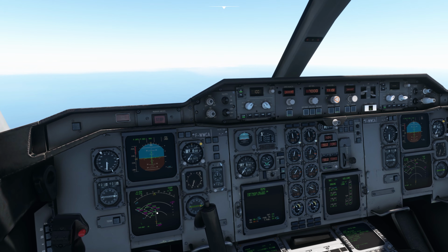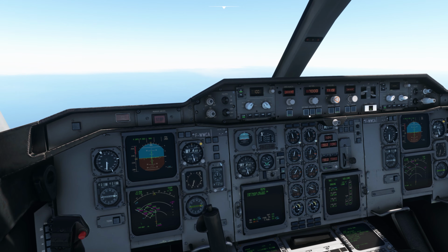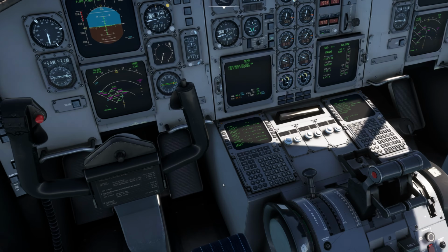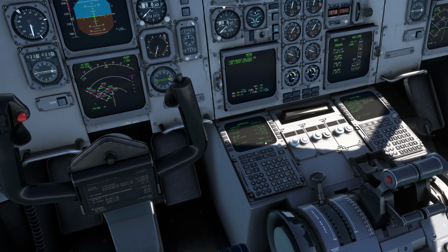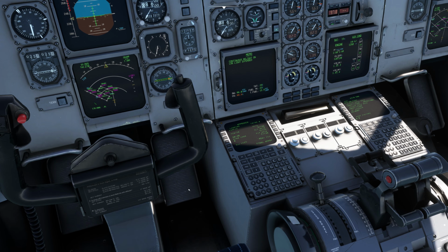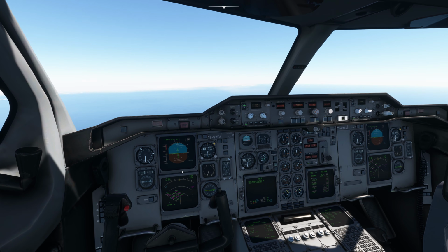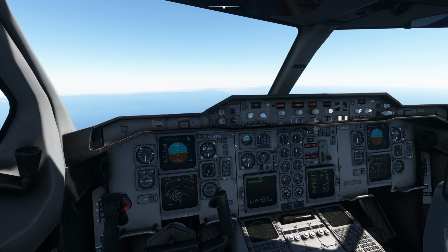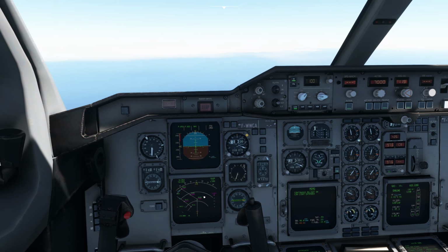So you can see that before this point I will descend to 7,000 feet, but if the profile mode doesn't do this, then you have to change it to level change or vertical speed mode. And let's bring up also the takeoff and approach, the final approach. I can press this button in order to activate the final approach. The speed will automatically reduce to 127 knots. Let's see if it works. I should be in the profile mode to do that, so that's why now I'm using the profile mode, not the level change or the vertical speed mode, because then the speed will automatically be adjusted by the autopilot. I don't have to adjust it over here manually.